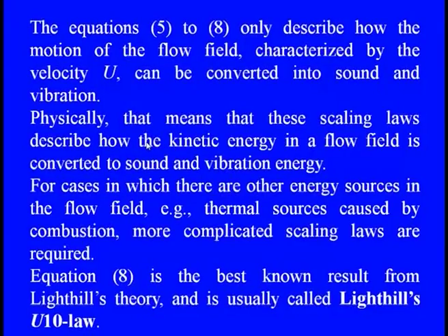For the cases in which there are other energy sources in the fluid flow, like thermal energies from various sources, such as combustion, we need to incorporate these features in the scaling law, which makes the scaling laws somewhat more complex. Right now we are only looking at the flow velocity and the sound velocity, and comparing them to characterize the fluid motion and to understand the basic physical meaning of vibration generation.